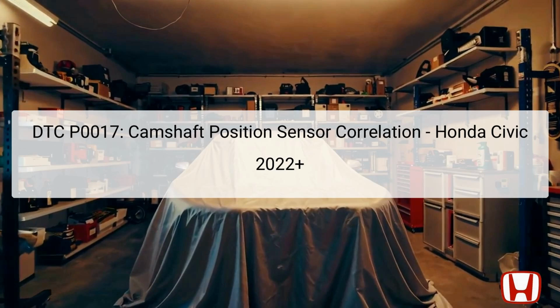In this presentation, we will thoroughly investigate Diagnostic Trouble Code P0017, which indicates an issue with the camshaft position sensor B and crankshaft position sensor correlation on the Honda Civic model from 2022 onwards. This code signifies a fault in the timing of the exhaust camshaft based on data received from CMP sensor B in relation to the standard exhaust camshaft timing metrics.